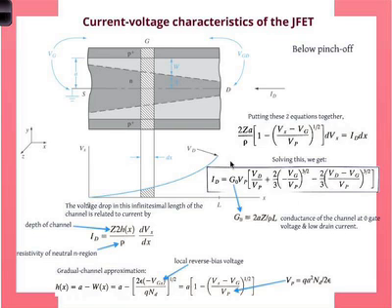You get essentially a current voltage curve which looks like that. But recall that the output is the drain to source current, ID, the left-hand side of that equation. Just look at this one for now. And you have two inputs, because there are three terminals, remember. The two inputs are the drain to source voltage, which is typically a bias voltage, or you can call it an input, and the gate to source voltage, which is typically the small signal that goes in for processing, signal processing or digital processing or whatever.